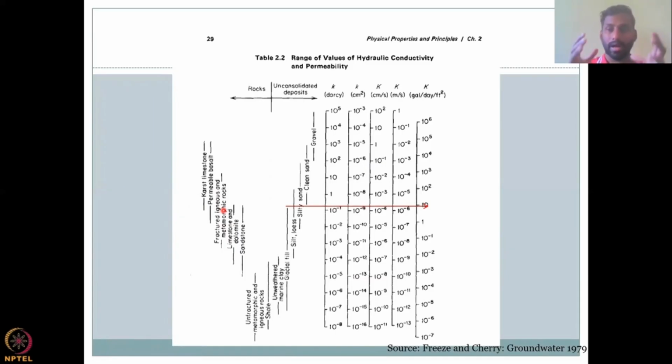The hard rock aquifer covers more than 60% of the area. So we're going to take that as an example to understand hydraulic conductivity. We'll use centimeters per second or meters per second to discuss the results. So you see that it is anywhere between 10 minus 4 to 10 minus 3 centimeters per second.